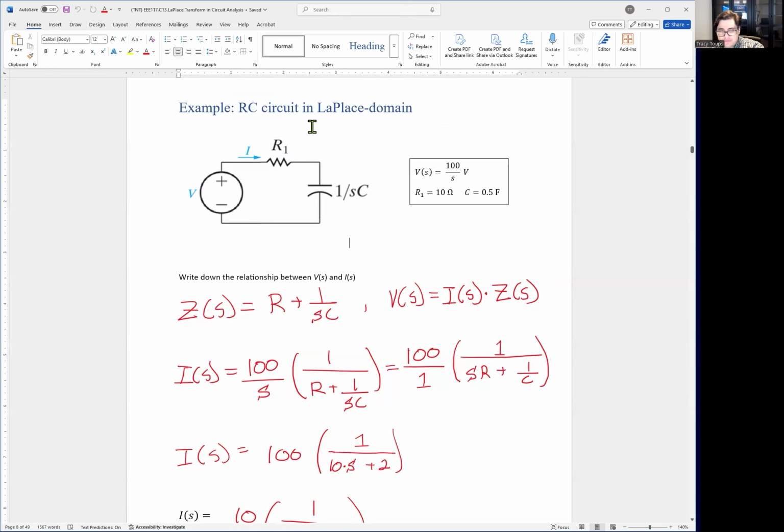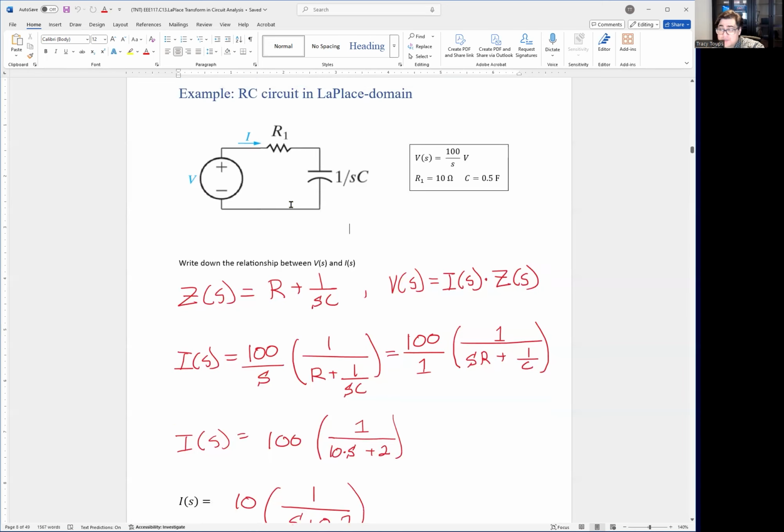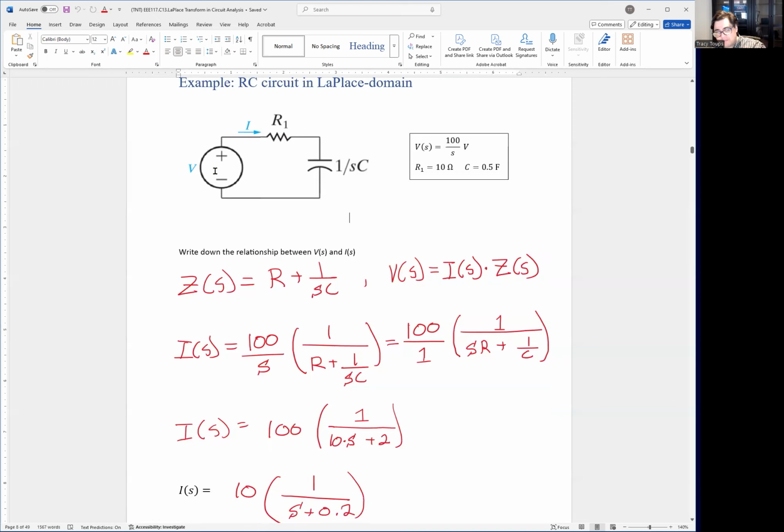Okay. So remember, the whole point of this circuit analysis is finding the current in terms of circuit parameters and frequency. Because when the time comes to use this, we're going to plug in a certain frequency for the voltage, right? It could be 100 hertz, 200 hertz, 300 hertz. We might have a little function generator with a knob where we're going to turn from 100, 200, 300, 400, 500, 600. And what we want to see is the current change as the frequency changes. Because a lot of times when we're using cell phones and communication equipment where we'll be hot swapping frequencies all over the place, I need to know how a circuit operates when frequency changes.